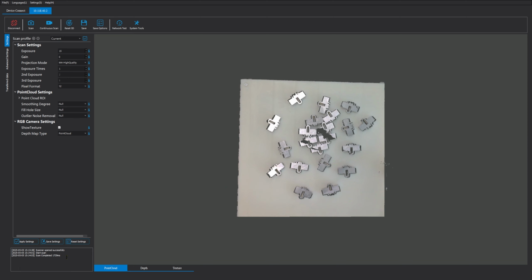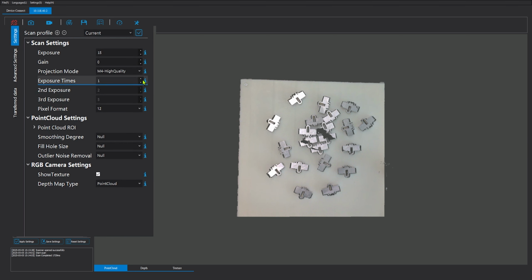And it makes great sense because these particular surfaces are positioned almost directly beneath the scanner, and they reflect a lot of light straight back, which can easily lead to overexposure. But to fix this, we can use high dynamic range or HDR scanning.